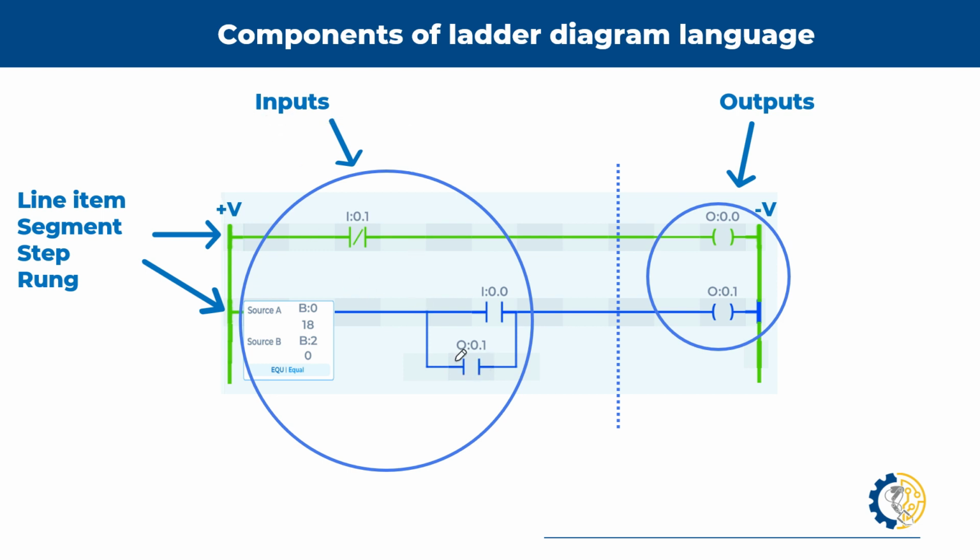Now this is an indicator for us, which tells us if it's on, if my motor is on, or my fan, or whatever we're using. So this tells us if finally we can power on that fan or that coil, and this is where we're going to allow the signal. Now, what I'm trying to get to is everything on our left side is input. Everything on our right side, which is generally devices to control or actions that we're going to run within our PLC. There are also instructions, for example move, which is one of our math instructions, which are actions, and they're also on our right side. We're going to look at this further down.